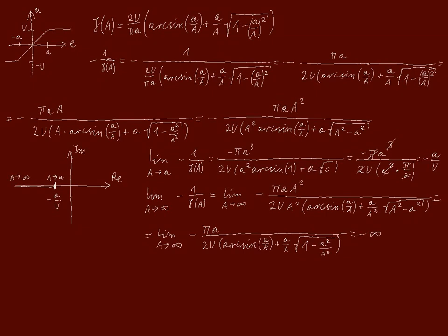This is a final graph of the describing function inverse. Please remember that all points of interest should be marked correctly so that we know their coordinates. In addition, you need to write where the limit is. That is, that large A tends to small a and large A tends to infinity. The last element of the graph that cannot be forgotten is the arrow, which indicates in which direction the amplitude A increases.